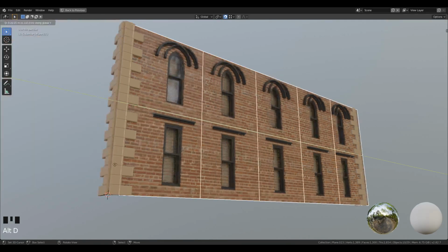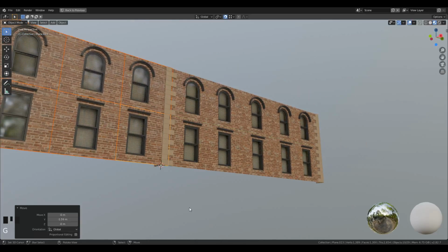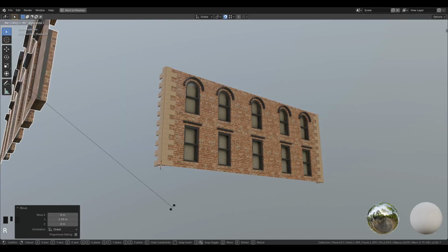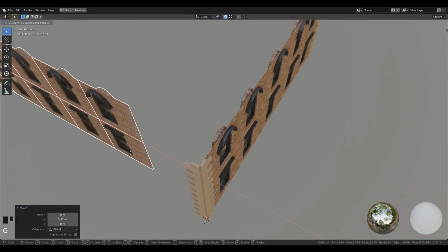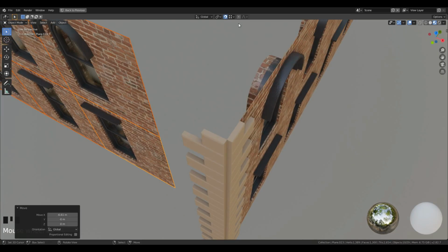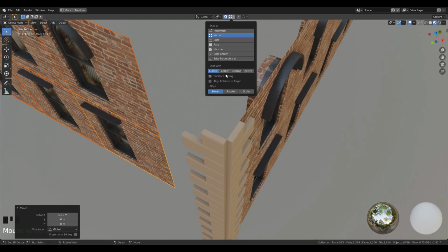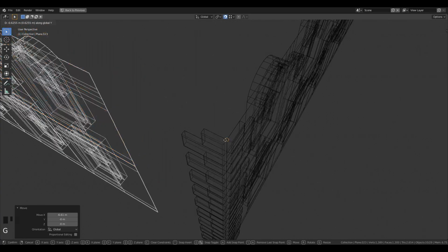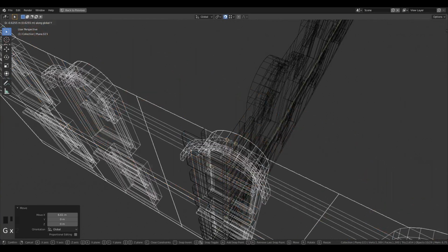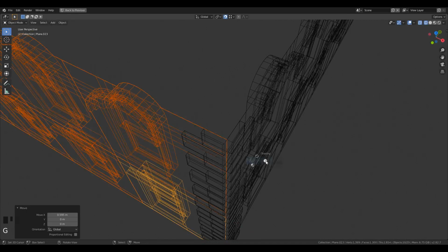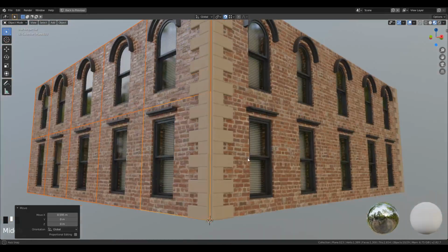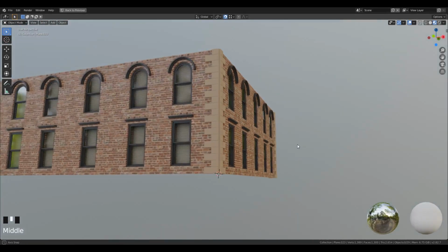Now just select the window panels and duplicate their instances by 90 degrees around the other sides to make a building. Use the median point in the snapping tool to snap the midpoint of the asset to the corner and then change the snapping to vertex so that it will help you while snapping these panels on the corner. Otherwise you will face snapping problems.